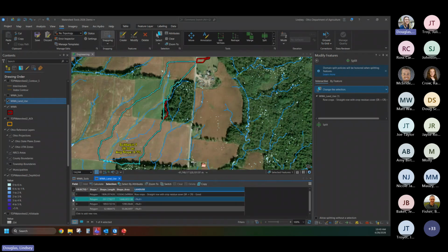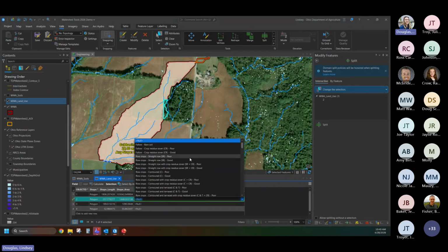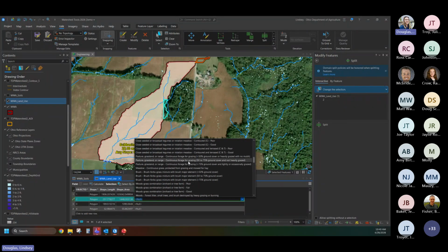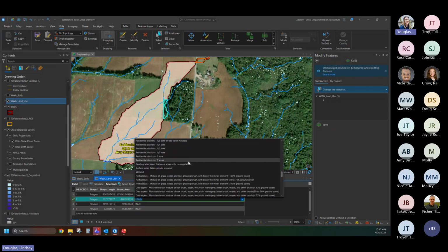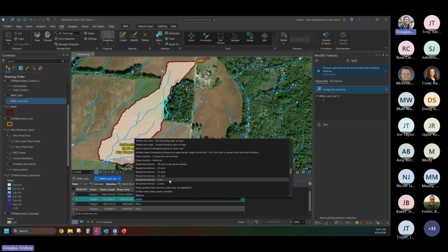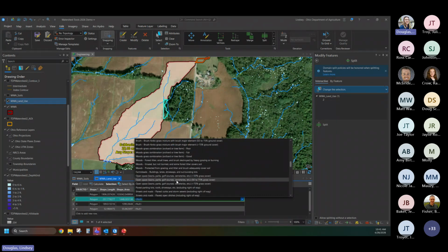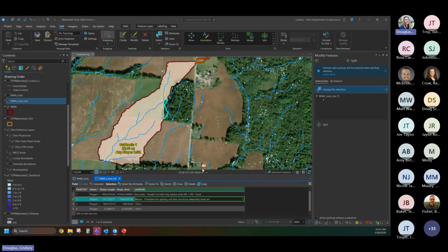The next one here is going to be the wooded area. If you guys explore this, you will notice it's a little bit different than some previous releases. And if you get far enough down, you will see, actually, here, I'll just show you. We've got Puerto Rico, Hawaii, and Florida designated areas specifically. There's just a little bit. These are pretty similar, but there are more and different options. So if you're very used to it, just take a minute and read through them. For this, we're going to do woods. It's protected from grazing and it's got litter, brush, and adequate soil cover.